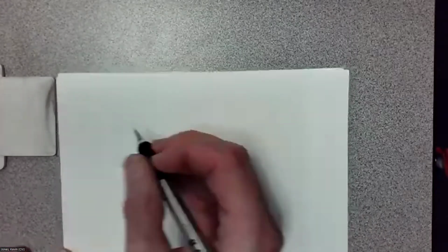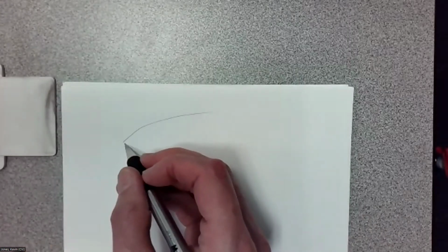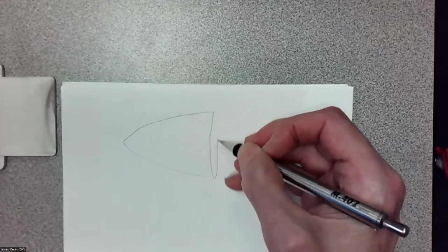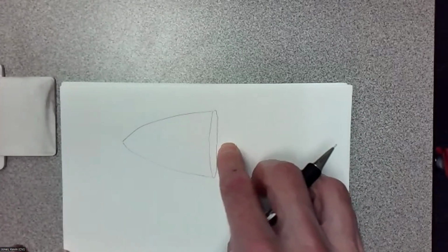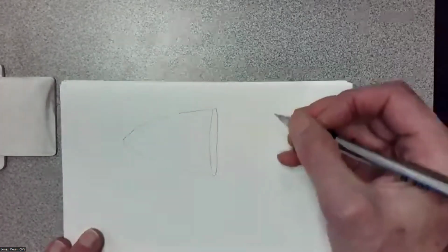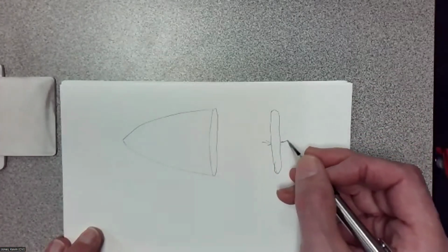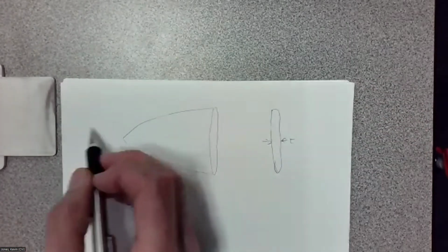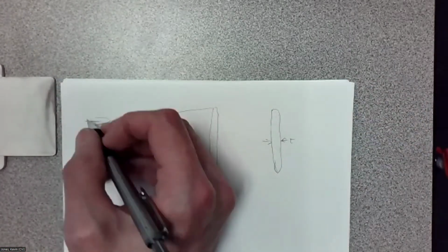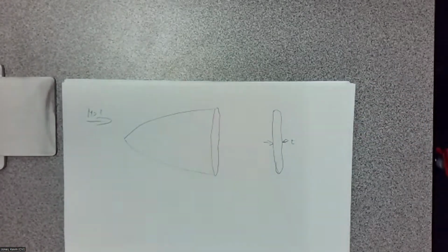Good. So let's see. Let's get on to some slightly newer stuff. We can use that same approach. It's kind of an added mass approach for say a slender airfoil. Say it's a wing. It's got some cross-section area. It's not a body of revolution, so look at it from the back. Say something like that. It's got some thickness to it, and it's going at supersonic flows. So we can apply the same approach. Again, it's assuming added mass.